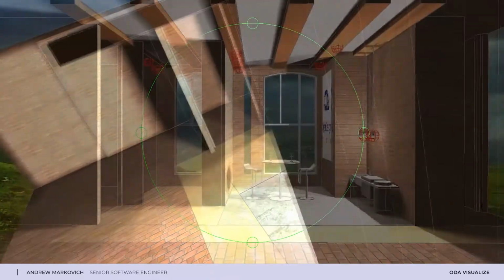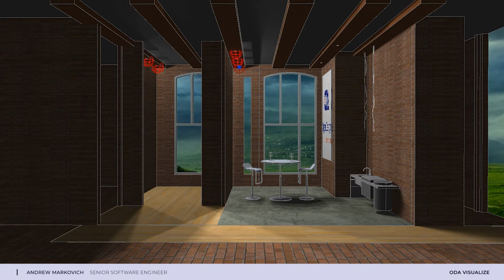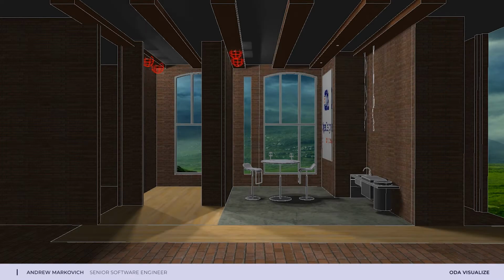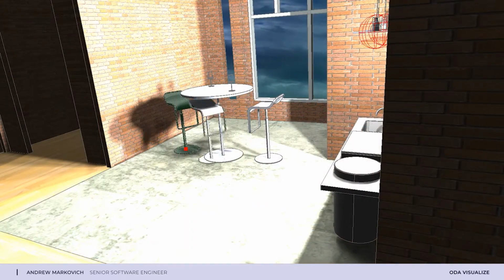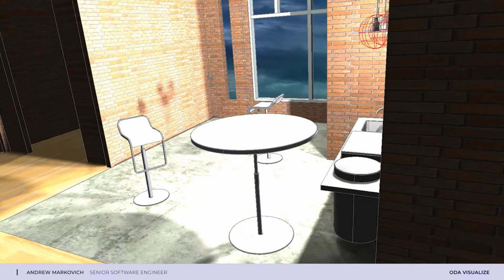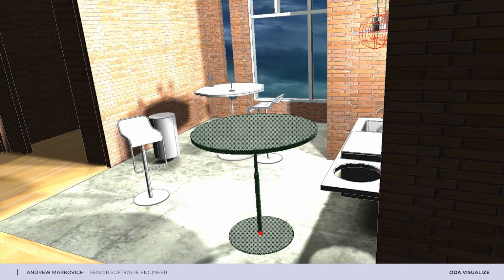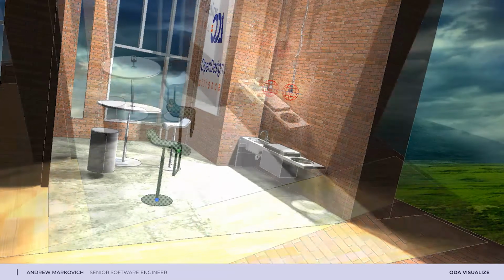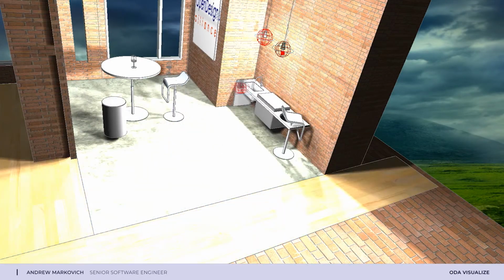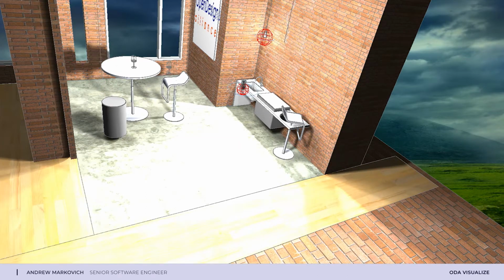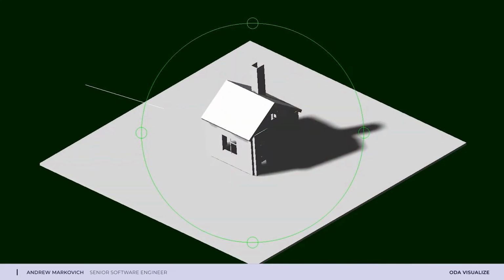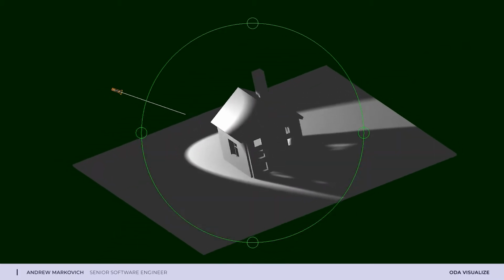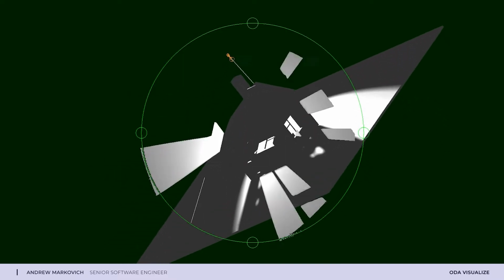For all of these platforms, we have stable rendering performance, since each light source shadow map requires only a single simplified graphic scene rendering for preparation, and usage of shadow maps during rendering doesn't visually influence the entire scene rendering performance. In ODA Graphics Engine, we can simply modify any light source properties and shadow parameters, enable or disable lighting, move light sources, or graphic scene objects. During graphic scene modification, all dependent shadow maps will be dynamically recomputed, and we can see the final result with shadows immediately. Of course, rendering performance depends on graphic scene complexity, but recomputation of shadow maps is done with simplified geometry details, so it doesn't seriously influence the entire rendering performance.